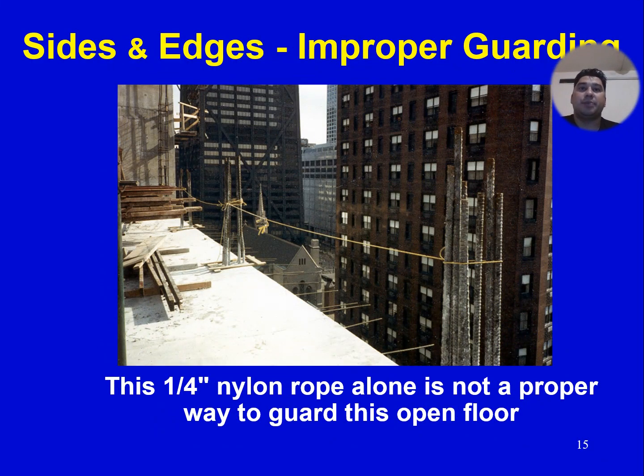On sides and edges, improper guarding. This 1/4 inch nylon rope alone is not a proper way to guard this open floor. The people are putting only one nylon rope, which is not suitable to guard them. So they can fall and get injured very severely.